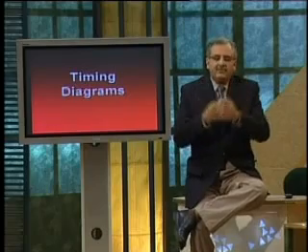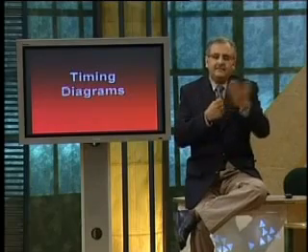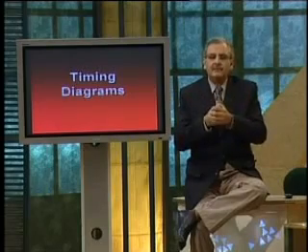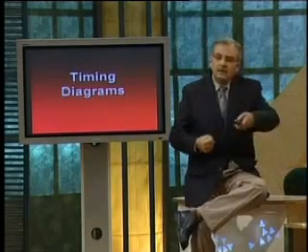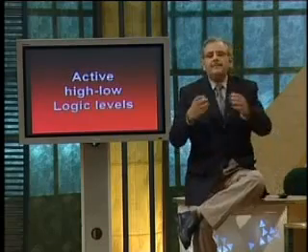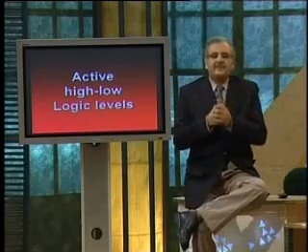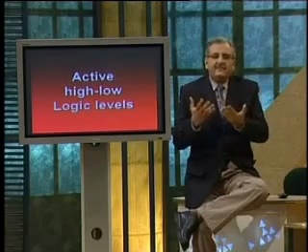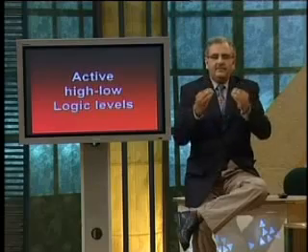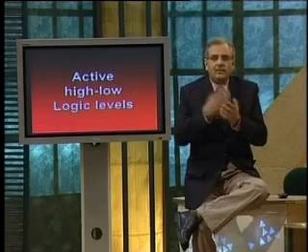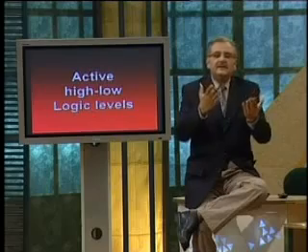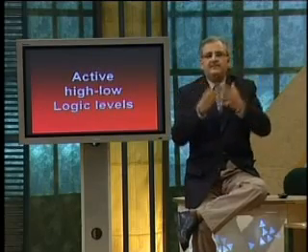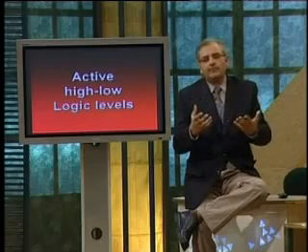Now let's talk about active high levels and active low levels. What are active high and active low levels? Up till now, we have talked about different circuits, for example, this particular circuit detecting adjacent ones. Now, if the circuit detects adjacent ones, what is the output? Basically, the output is 1. Well, we could have said that if the circuit detects adjacent ones, the output should be 0.